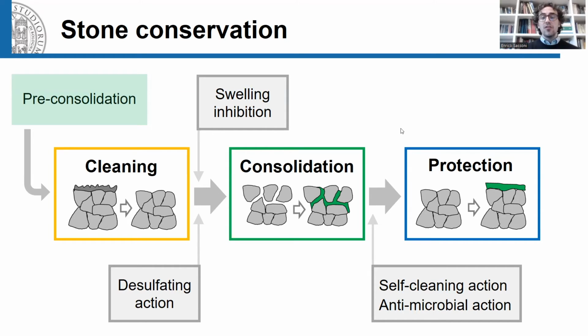After consolidation, we usually have the protection of the stone, which is the application of a surface layer aimed at acting as a barrier between the stone and the aggressive environment. Protection may be preceded or combined also with other interventions aimed at providing the stone with self-cleaning ability or with an antimicrobial action.